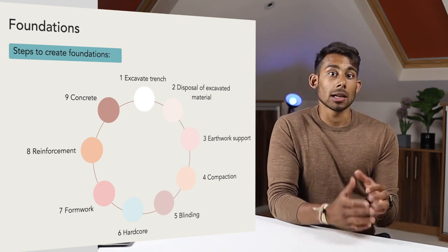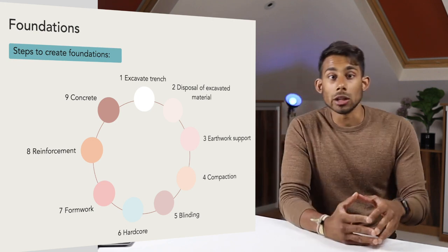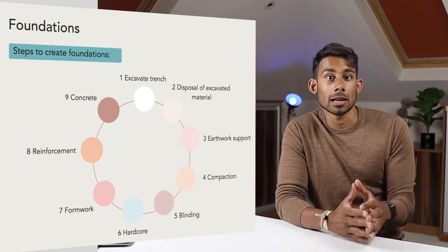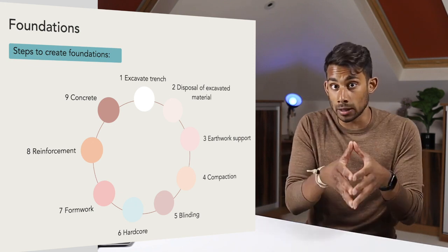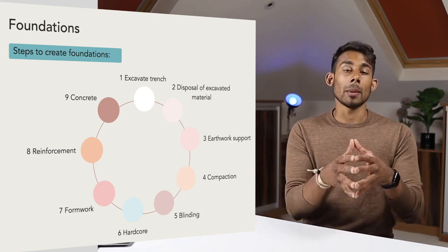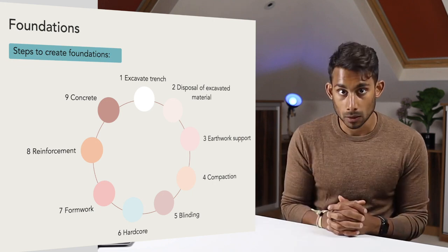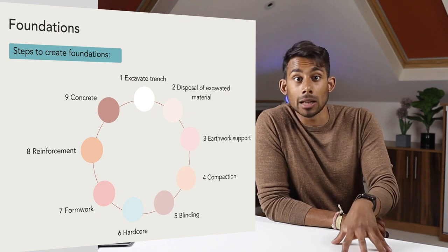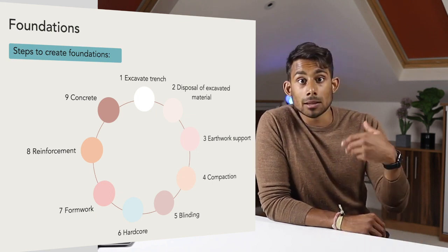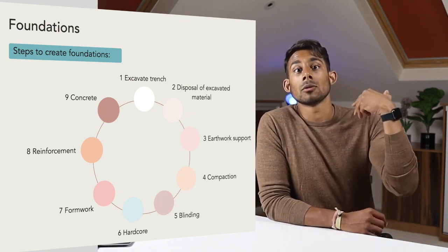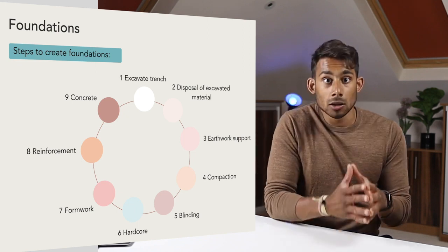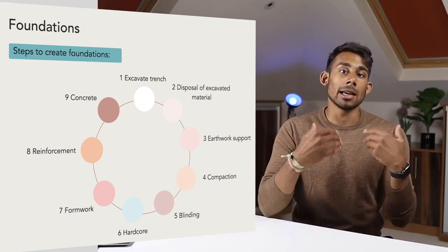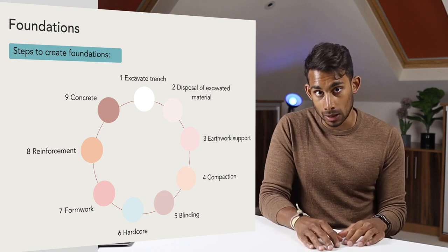Ready-mix concrete trucks have extension ramps that can reach around 3 or 4 meters. So unless the concrete can be offloaded at various positions around the site, you may need to use a concrete pump. If you are using wheelbarrows, manpower should be made available to speed up the job, as 1 meter cubed of concrete will fill around 30 to 40 wheelbarrows. Paths to the pour should be cleared and planks laid to deal with any slopes or uneven ground.